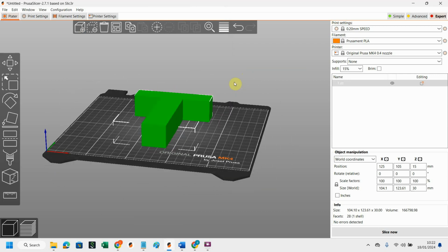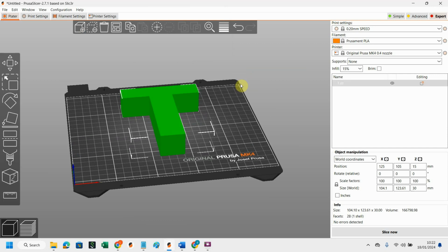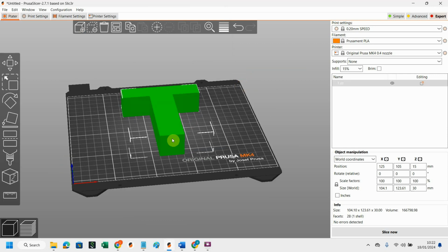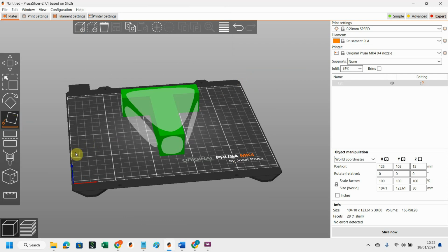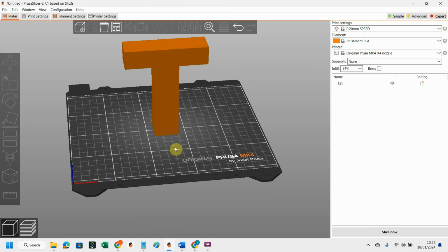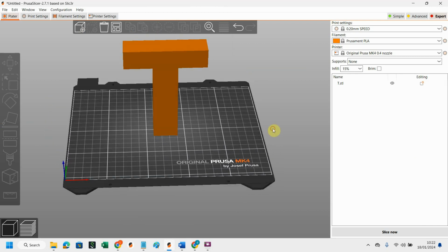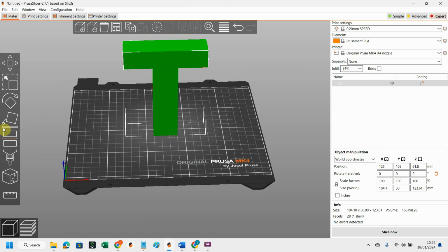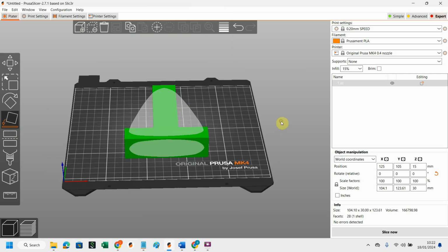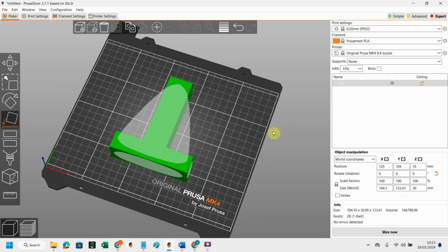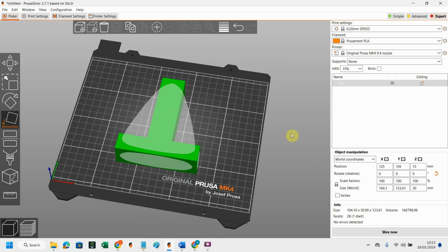and the part lands directly onto the build plate. If you need to orientate it, there's a quick way to do that here. If you select this option here on the left hand side, place on face. So select that, and if I click a face, it'll quickly rotate. Okay, and again, click on the part and click on face, and I can move things around quite easily.